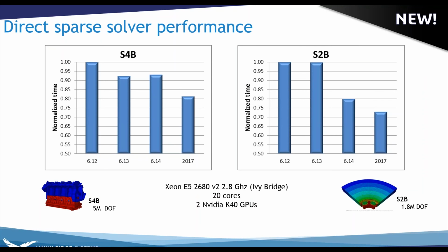The LCP equation solver is a development that allows us to look at contacts without any sliding contact in a new solver in Abaqus CAE, and what this offers is, if we have a small set of contacts, we see a 10x improvement in computational time.